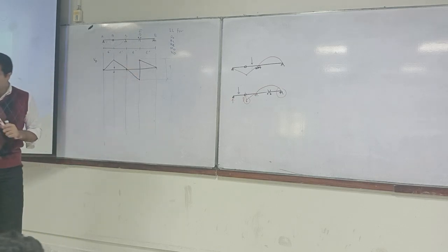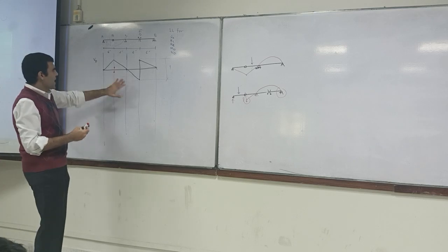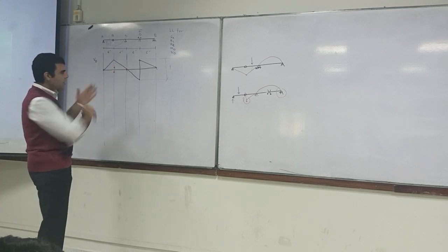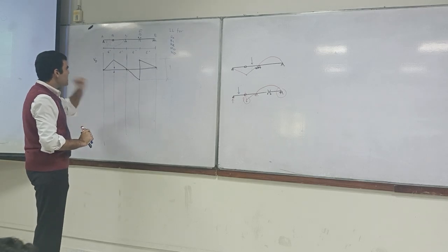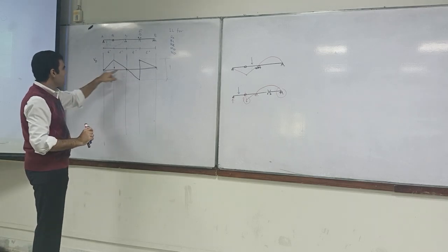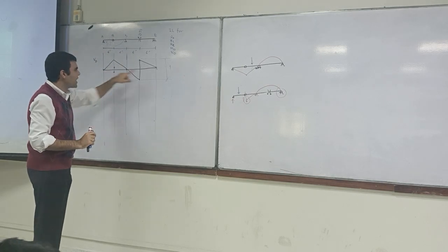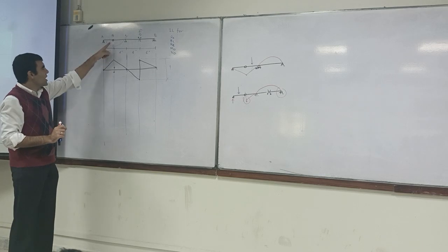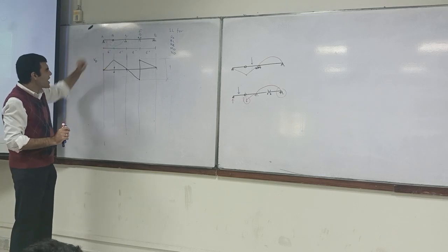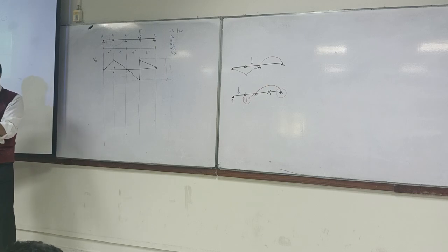Okay, so then what do you think? You think that whether I've drawn my influence line diagram linear. So check, yes, that's linear. Another thing is that all the kinematic boundary conditions are satisfied. Yes, this one, this one, this one. Yes, all three of them are satisfied. The internal hinge is moving up. Yes, that's satisfied.